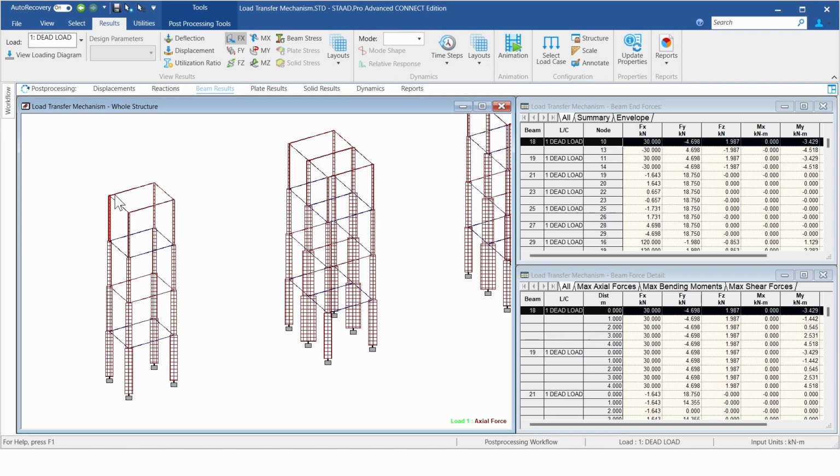And this 30 is very easy to understand. We have a 120 floor load on this complete floor that is being divided into 4 parts. So we are getting a 30 kilonewton load on this column only. If I move down, now I'm getting the load of this floor, or 1/4 of this floor, that is 30, plus whatever was above it, that is 30 again. So in this case, you can see we are getting a value of 60.